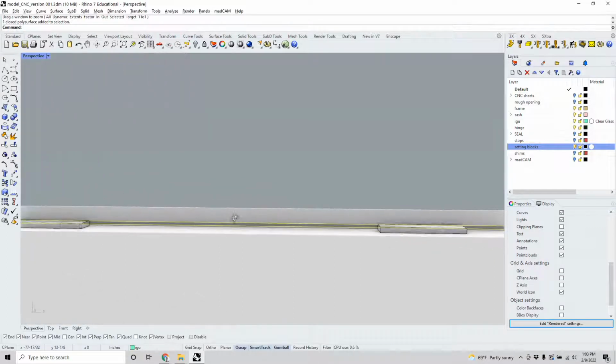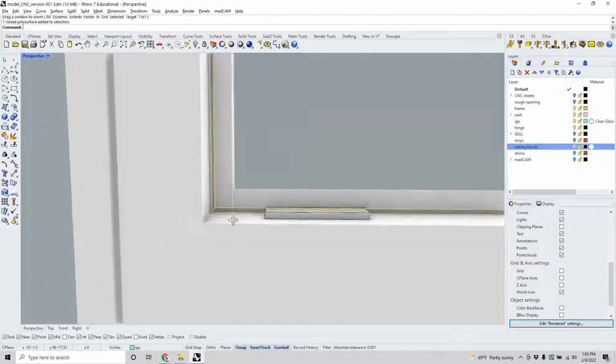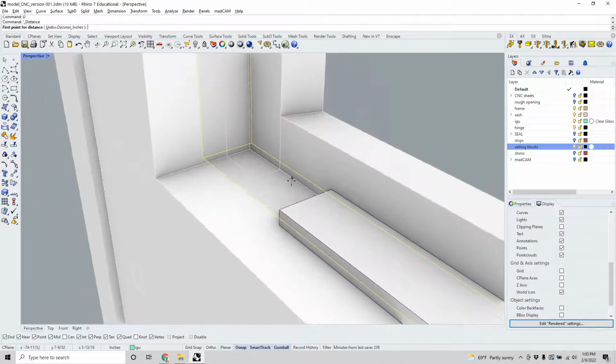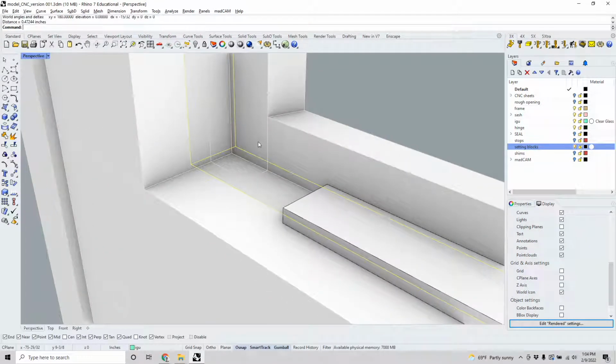And what I order is a narrow sightline, which is meant to be recessed in this half-inch rebate, such that this is about half inch, right? And similarly, this is about half inch. So all of the components, the metal that goes into forming the IGU unit, are slightly narrower so that they fit within this half-inch stop. I think the narrow sightlines are 3/8 of an inch. This way all you see is glass, theoretically, if you do it well.